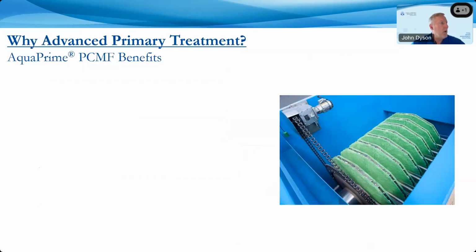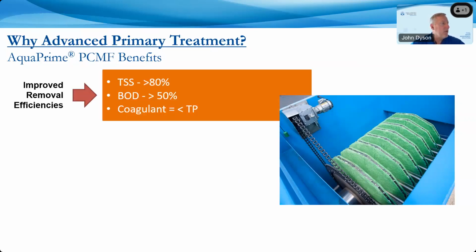All right, so what are you achieving with advanced primary treatment and the use of a Pile Cloth Media technology like the AquaPrime technology? So what you achieve here is without chemical addition, we have found we can easily remove 80% of the solids and generally achieve greater than 50% BOD removal, and respectively about the same for COD also.